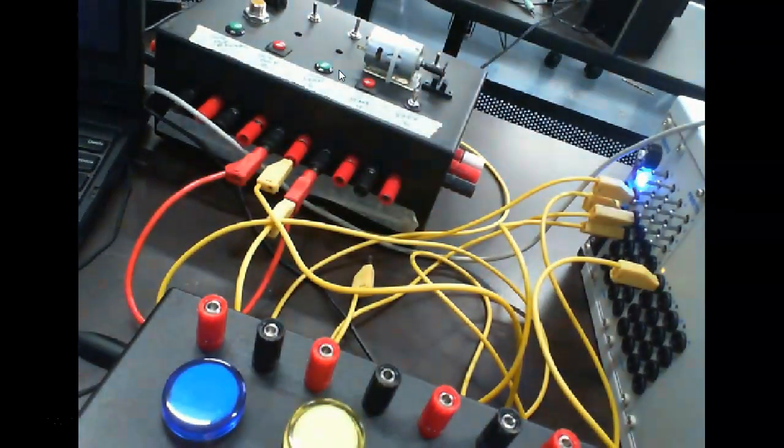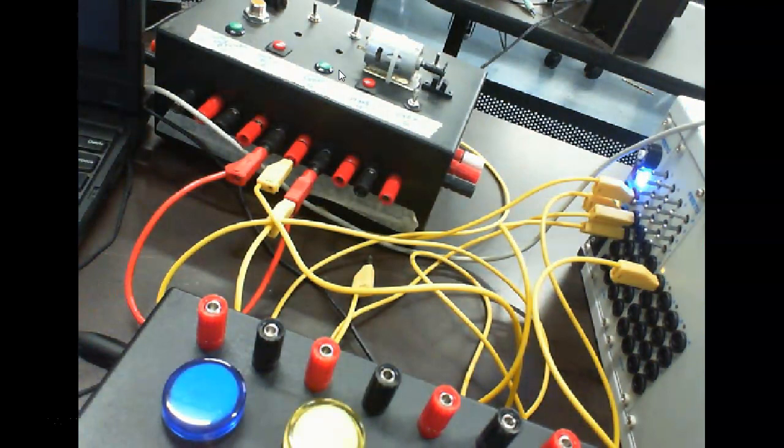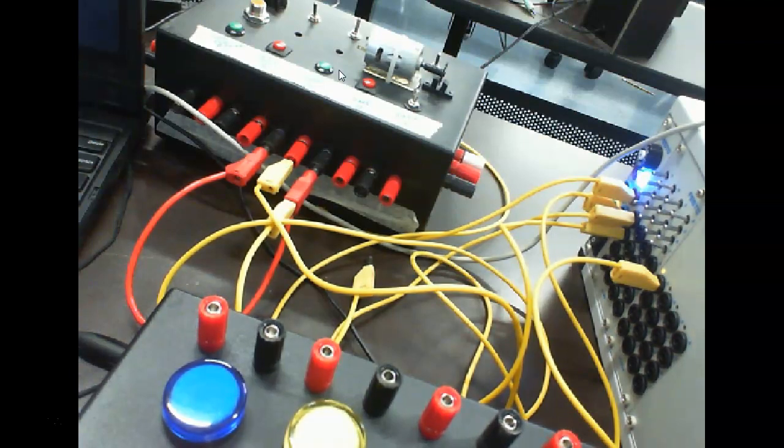So I'm going to start this thing up. And oh my goodness, I have a broke wire on my stop button. Can't stop my motor. I just killed all my workers, because I have no way of stopping the motor. Wires break in the industry all the time. So for wire breaks, what would you like this motor to do? Stop. And then you can fix the wire, right? Right now I got a motor running and I'm trying to troubleshoot this sucker.